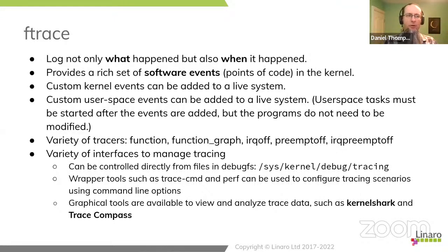That does not have the same property as cyclic test because things like firmware latencies cannot be observed using it. But it does allow us to measure very much the worst case interrupt latency by seeing how long interrupts are held off for. It allows us to look at the worst case scheduler latency by looking at how long preempt is off for, because IRQ off and preempt off usually dominate both of those latencies.